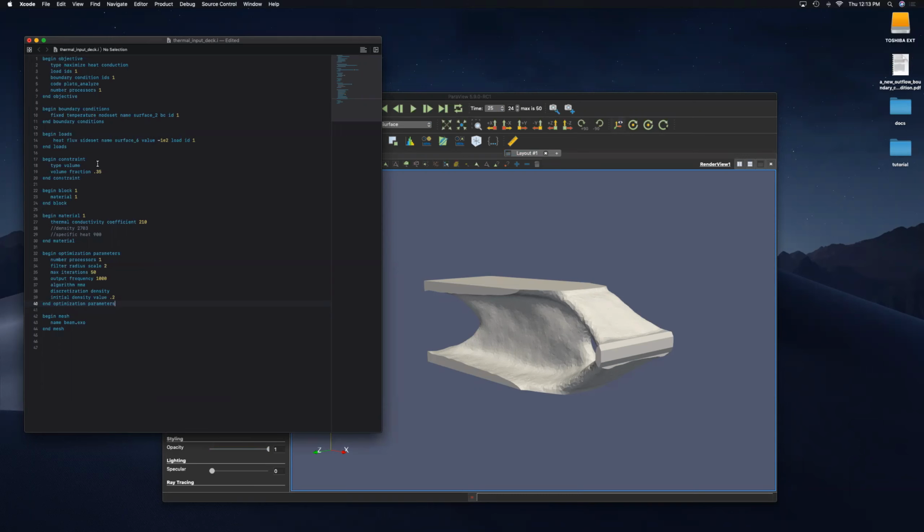Oh, well, the reason I'm asking this is because I noticed that the materials you specified don't have the density associated with them. And I'm guessing at some point you want to include the density if you want to take that into account. I'm not sure if I'm asking the right question. No, you are. So for example, for the stress problem, basically the formulation is minimize mass with your stress constraints.